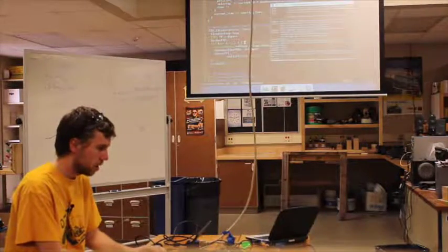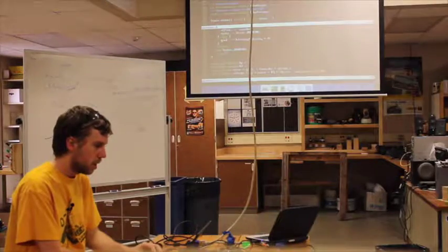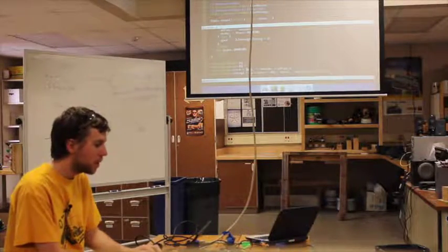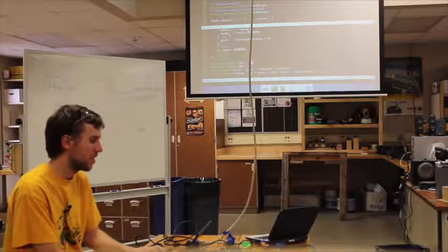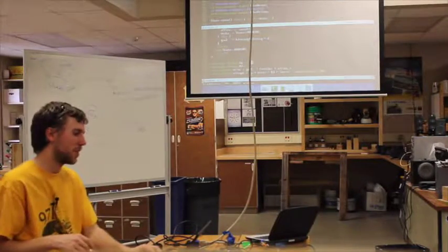Do you do the thing where you turn up KP until you get an oscillatory response? If you really want to know what I do, I don't use PID loops. I thought you used state space controllers. Yes, state space, and you push the limits in other ways.